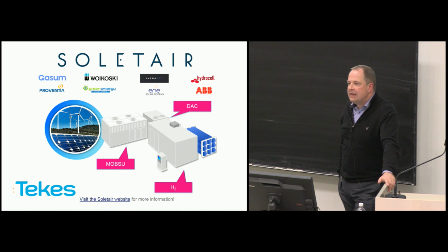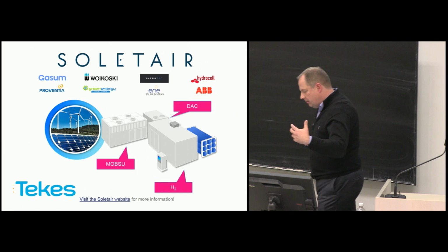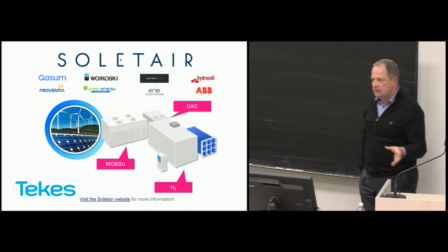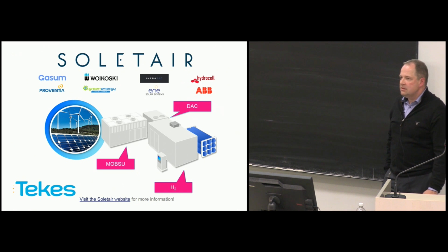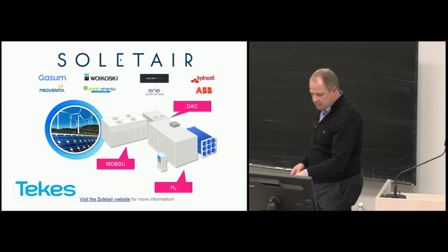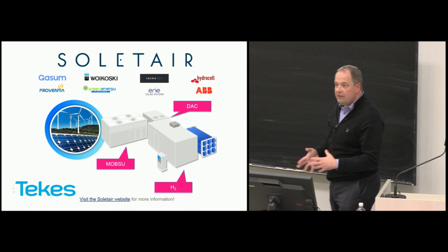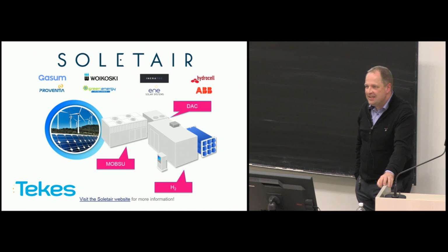Whether it will ever make a difference depends really on scale. If I remember right, you know the biodiesel plant in Lappeenranta by UPM produces diesel from tall oil. It produces about 100,000 tons of fuels, which is something like a few percent of Finland's fuel use. If you were to do that production using this concept, the average power demand would be something like 300 megawatts of electricity. So you need a lot of juice to do this in large quantities.